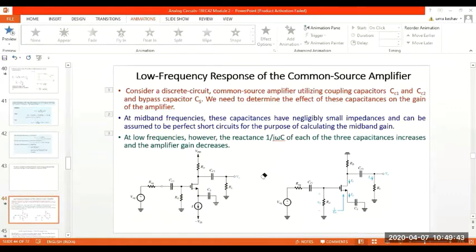So for the equivalent circuit, removing all these DC sources, we have drawn the second case. See here, for AC analysis, all DC sources act like short circuits, so this point will be grounded. Similarly, this current source will act like an open circuit, so it's not considered. The rest of the circuit is the same as this. For AC analysis, this is our equivalent circuit.